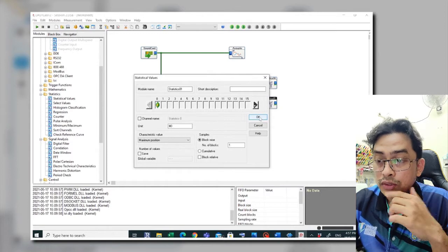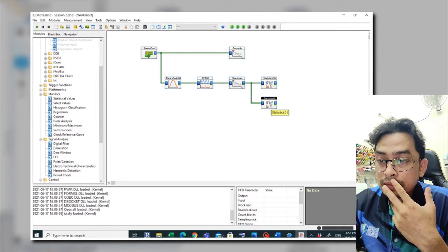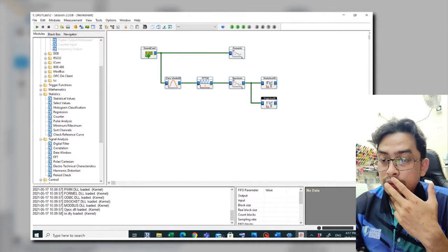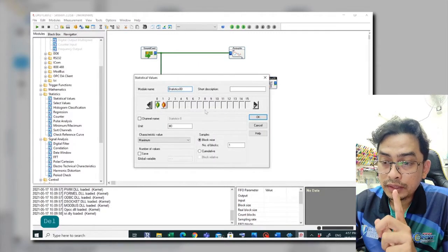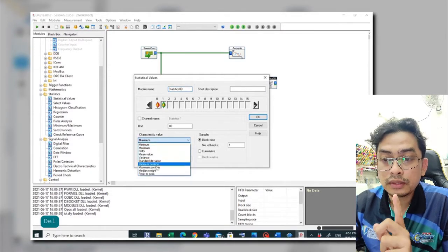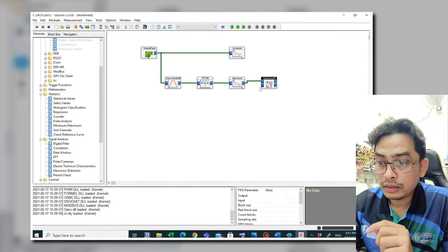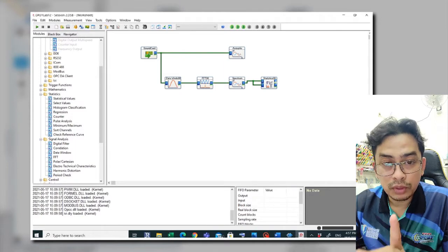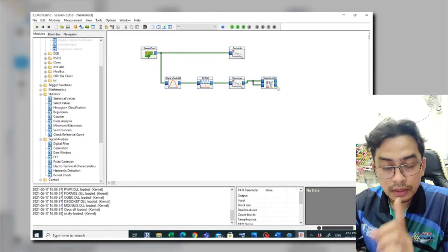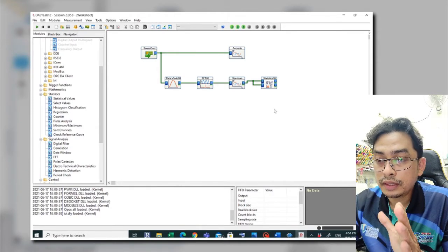So just click OK. Either we do this, or if you want to minimize the modules, we can do another way, like this one. So I just delete this one, I double click this one, I add one more channel. This channel is for the maximum value, and this channel is for the maximum position. Okay, so if I click OK, it will appear as two channels. So just bring this one, put it here. Okay, so 0 is for maximum and 1 is for the maximum position.